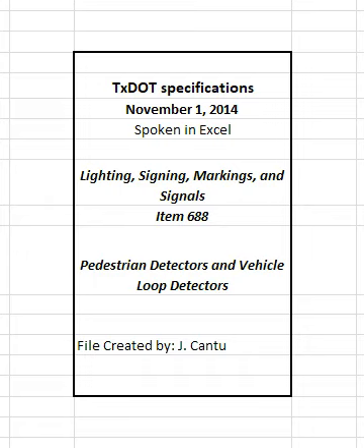Mount a pedestrian push-button sign near each push-button as shown on the plans. For installations where APS buttons are placed less than 10 feet apart from one another, program the appropriate speech walk message, include the name of the appropriate street in the message, for these buttons. When two APS buttons are installed on the same pole, ensure that the APS buttons are insulated to eliminate vibrations from traveling to the other button.